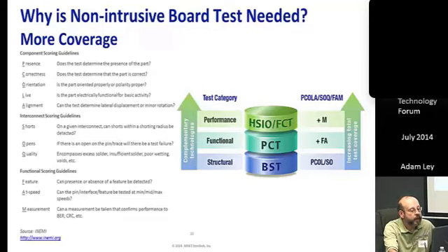So embedded instrumentation can come in and of course pick up your structural testing, what iNEMI calls the PCOLA: presence, correctness, orientation, aliveness, alignment. Embedded instrumentation can also pick up your interconnect shorts, opens, and quality, which are also structural aspects.